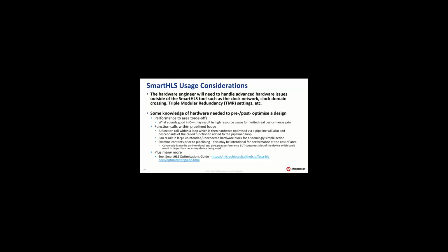If you do it incorrectly, you can end up with a piece of code which is very highly optimized and runs beautifully quick in the FPGA, but takes up most of the device. And that may be one of those unintended consequences of not looking at what it might do. So you can't just go, write C, throw it in, done, job finished. Write C, apply common sense and logic.